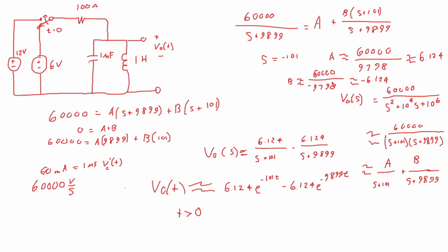And so this is the reason that it's important to talk about underdamped versus overdamped versus critically damped. Okay, this circuit is overdamped. And so the resistor here is very large, which is what happens when you're dealing with an overdamped situation.